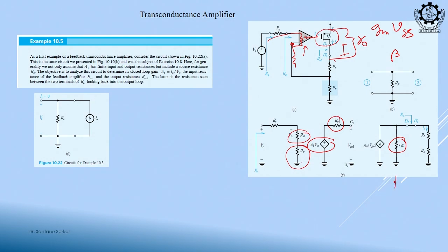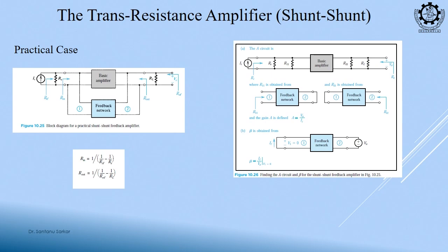We have done the two-port network of BJT and MOSFET, that is also added with another amplifier that we have done in the first chapter, right, the amplifier section. So, if we structure this step by step, then it will become easy. So, we discussed the basic feedback amplifier and their input and output impedance. Now, this RS we can have as a source resistance, this we can have as the input impedance, this we can have as the output impedance of this basic amplifier, and this is the load resistance. Okay. Step by step we will consider.